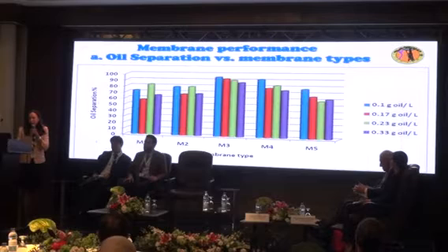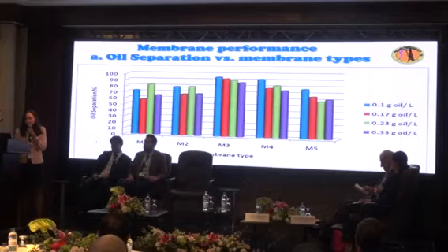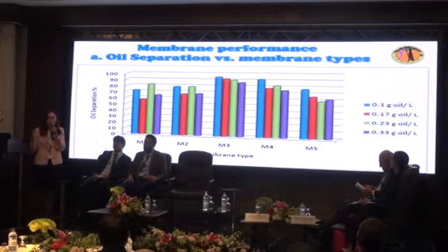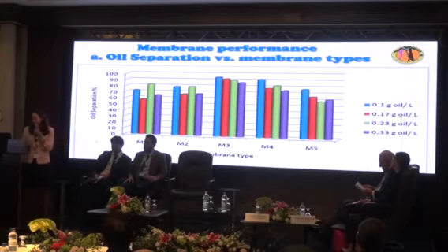And the most important thing is that when I tested these microfiltration membranes for oil separation, we found that by using 0.5% PEI, you can reach 92% oil in water separation. So your water at the beginning of the first stage is totally or almost totally free from oil, with a percentage of 92%.